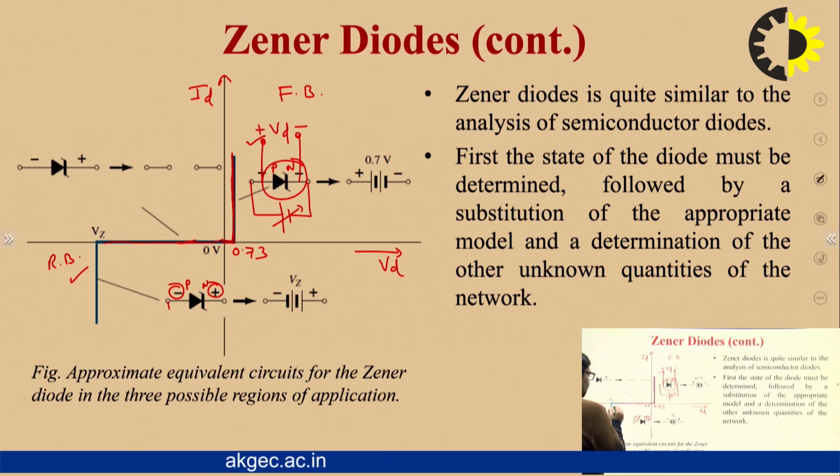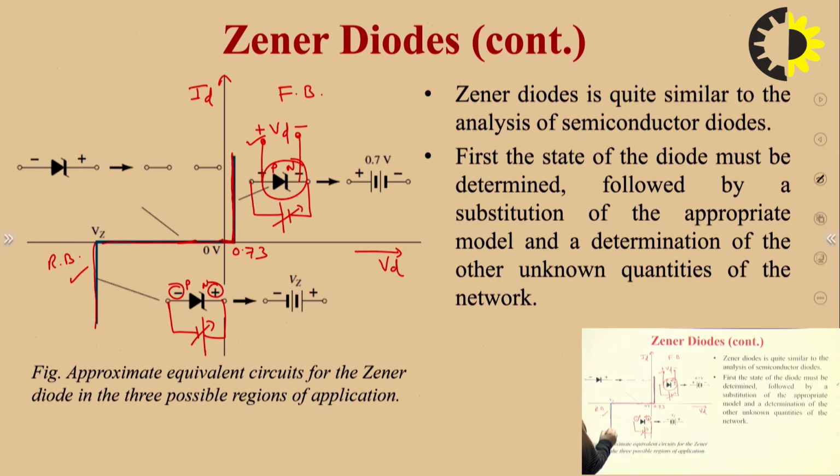If we increase this bias voltage, a heavy current flows in the reverse bias manner. Such current is called the Zener current in the breakdown region. In the reverse bias region of the Zener diode a heavy current flows, but the voltage remains the same.